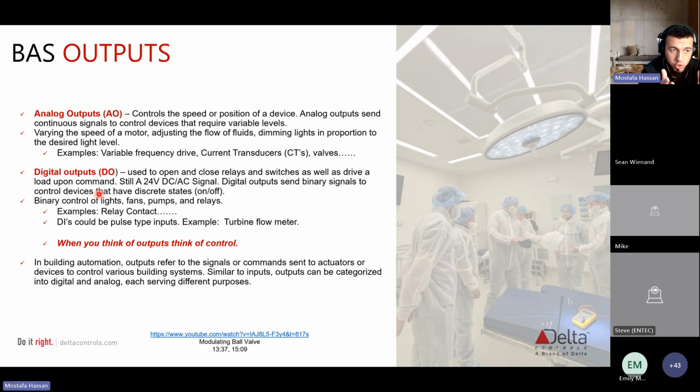This also works. The proportional side from analog works also for valves, right? Depending on how much you want the valve to open up, that'll also be calibrated to an electric signal, right? So you'll calibrate it based on 0 to 100, 0 to 10 volts. Depending on what position you want the valve to be, that voltage will be read at the controller level. And then digital output, again, opening and closing a light switch, deciding to open up the valve. That's also a DO, right? Open the valve, and then you can control it proportionally through an analog output.